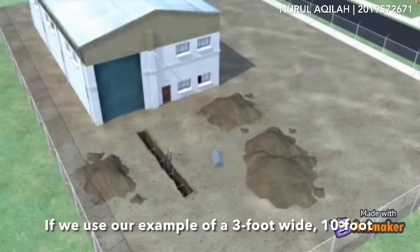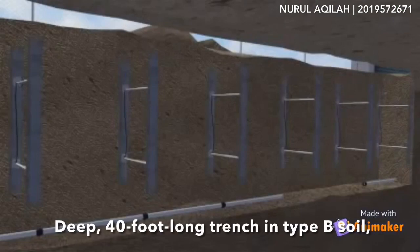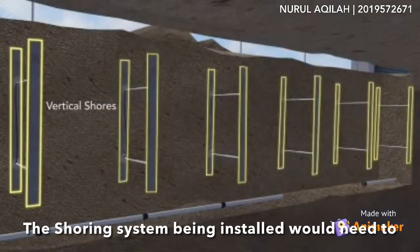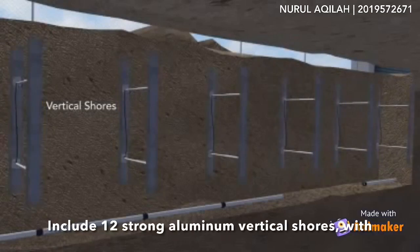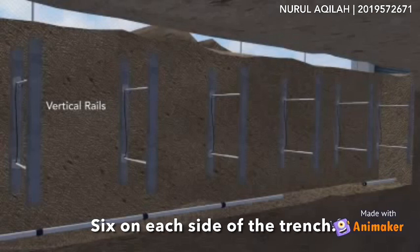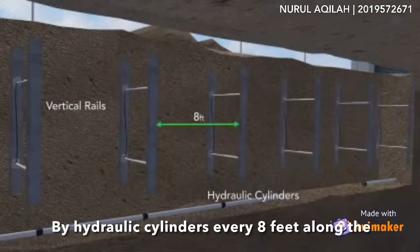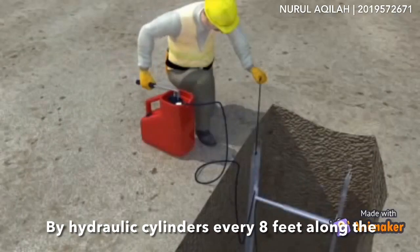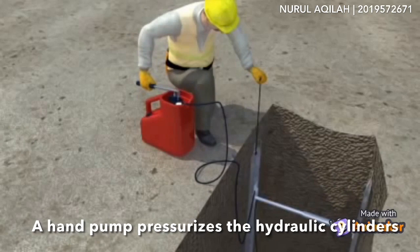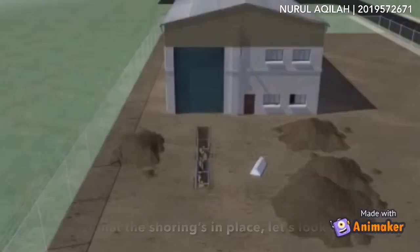If we use our example of a 3 foot wide, 10 foot deep, 40 foot long trench in Type B soil, the shoring system we install will need to include 12 strong aluminium vertical shoes with 6 on each side of the trench. These shoes, also called rails, will be connected by hydraulic cylinders every 8 feet along the length of the trench. A hand pump pressurizes the hydraulic cylinders until they fit tightly within the rails.